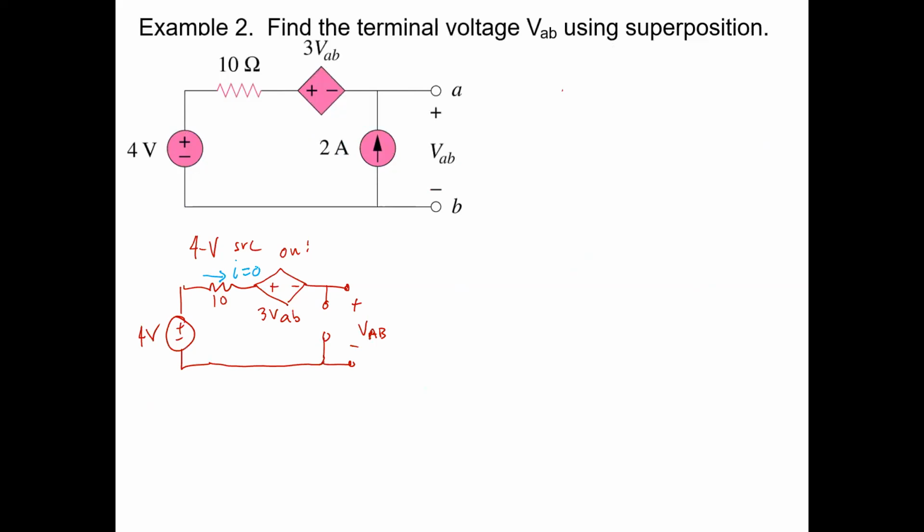Isaac. Does that mean that the voltage across a specific element would be zero? Yeah, and specifically the resistor, right? So that means when you do KVL, you can say -4 plus, well, the voltage drop across the 10 ohm resistor is 10 times 0, right?